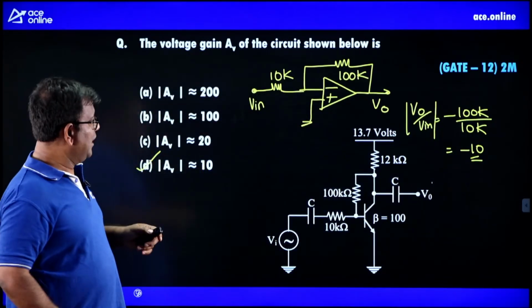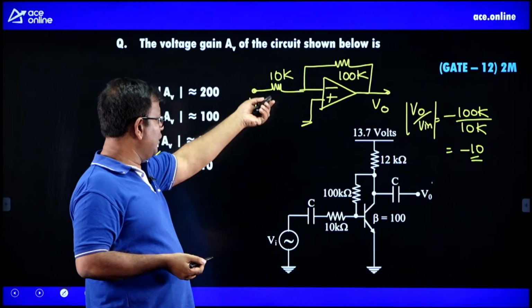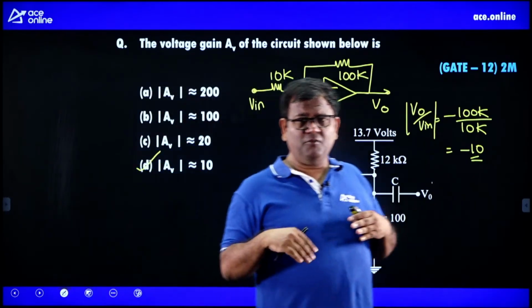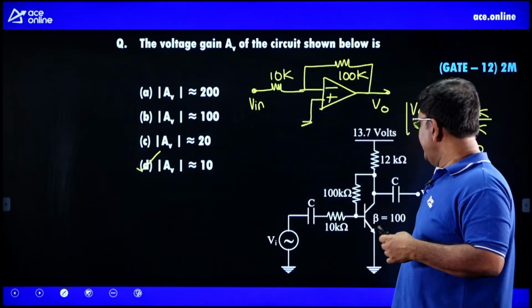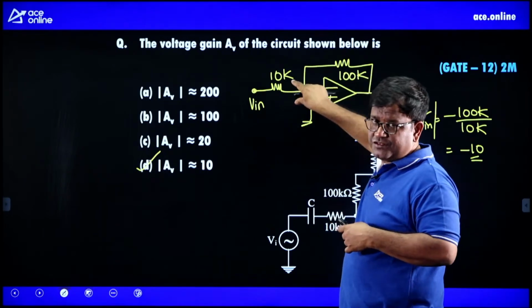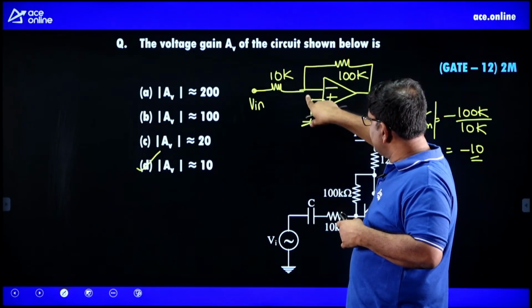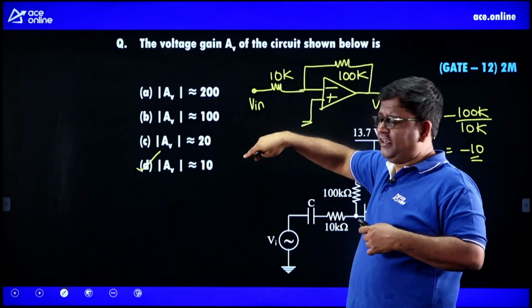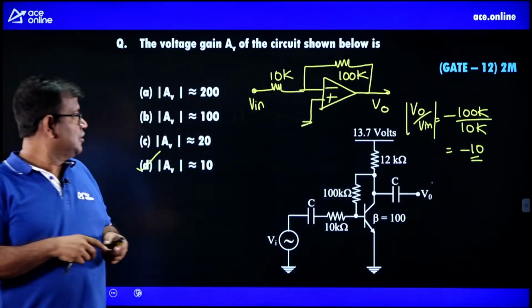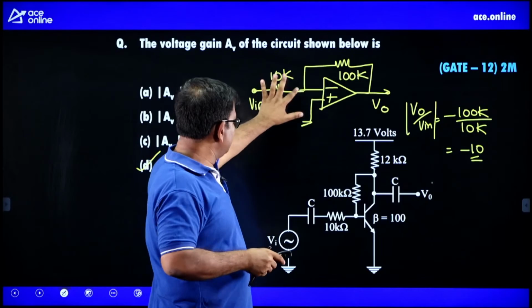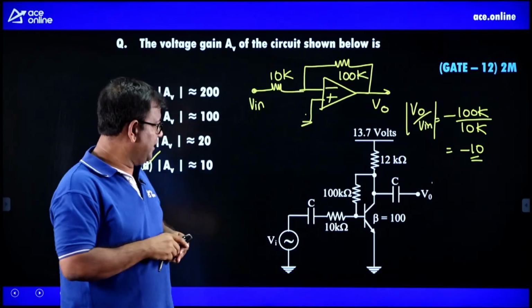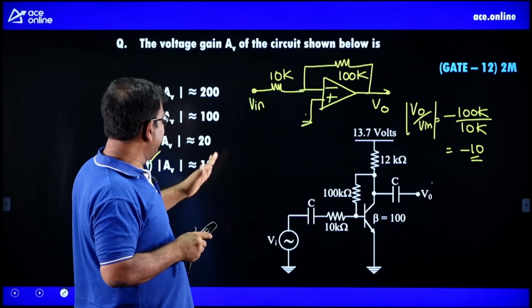So that's the solution. But how do we arrive at that? Because the examiner has not given an op amp, he has given a BJT here. Whenever there is negative feedback, the voltage between the two input terminals is going to converge, and the voltage at this terminal is going to appear here because of the feedback by backtracking. That is something we lightheartedly call virtual ground, or virtual short. This potential appears here. So you can apply the same technique here, and look at the unnecessary data.